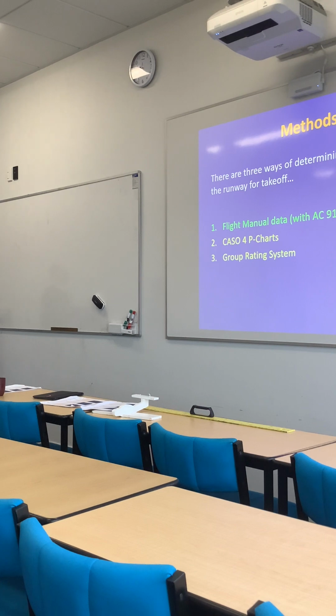So let's talk about the group rating system. This is unique to New Zealand. Every aeroplane that is imported into the country now is given a number from 1 to 8, and it indicates the typical performance or the takeoff distance required of this aeroplane. A low number, for example 1, indicates the aircraft has good takeoff performance, as in it can get airborne in a short distance. A group rating that is higher, say 8, indicates an aeroplane that needs a long distance to